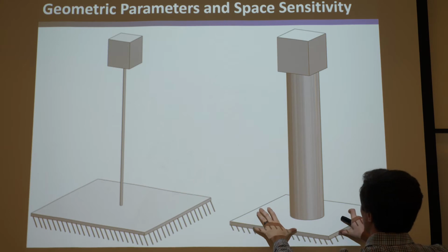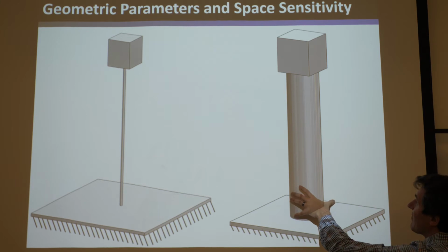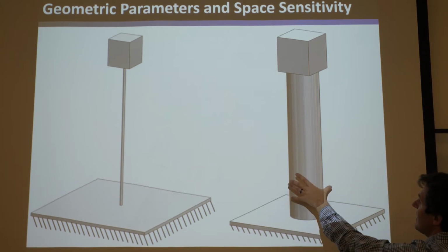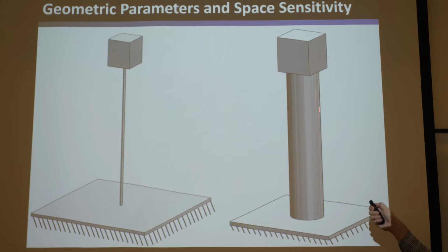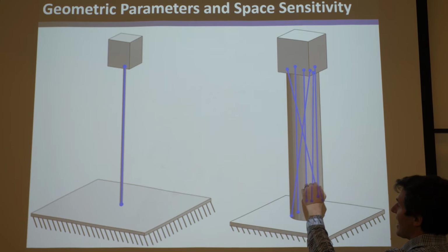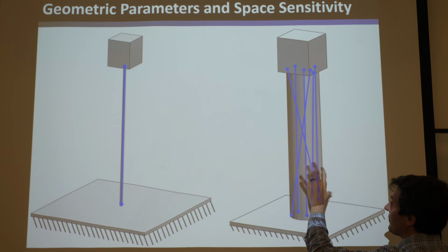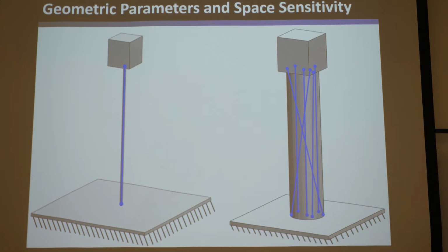And if this is the ground and that's the stage, and you join this, you'd instinctively know this is so big and fat and comparatively short to its diameter that this would totally lock this up at a constraint. It'd be totally exactly constrained. There would be no degrees of freedom on this guy, and you know that because what you do is you draw the blue lines that connect the ground to the stage that pass entirely through its geometry without exiting it, and fill it. So you could totally fill it entirely blue.